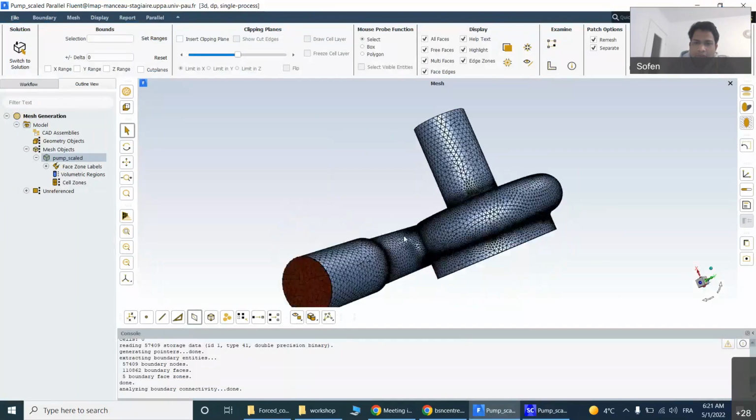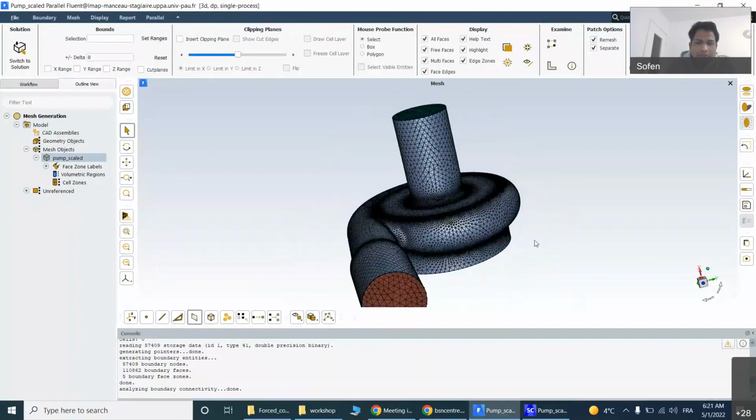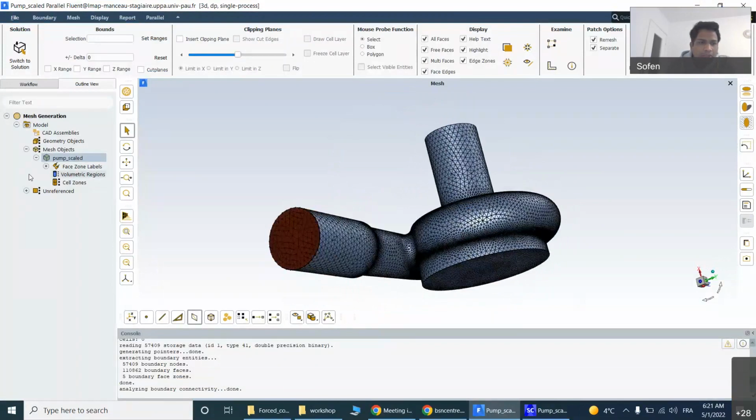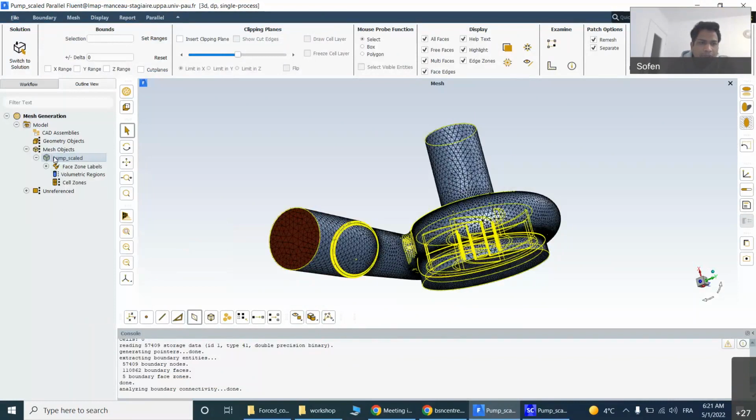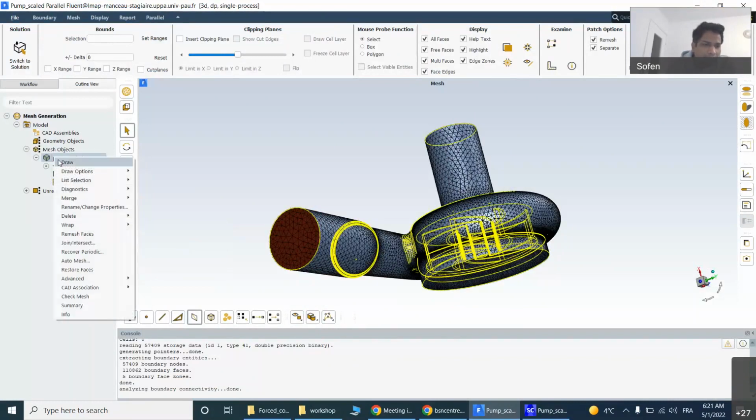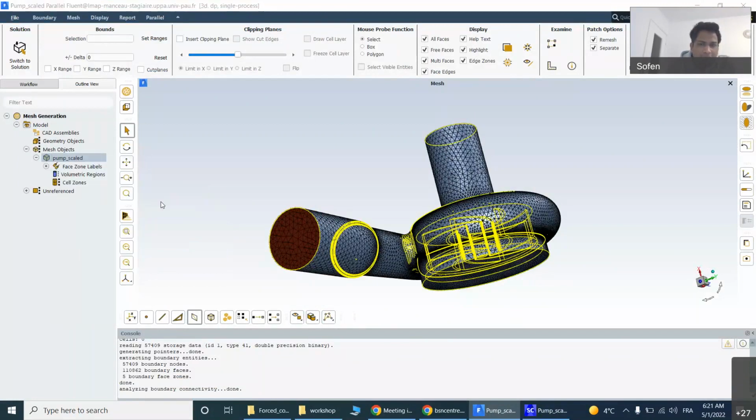Okay. So to volume mesh it, let's see how many parts are extracted over here. First, assume everything is correct, there may be some T faces or some free faces or something. How to check that? Yesterday I showed you. Right click, Diagnostic, connectivity quality.